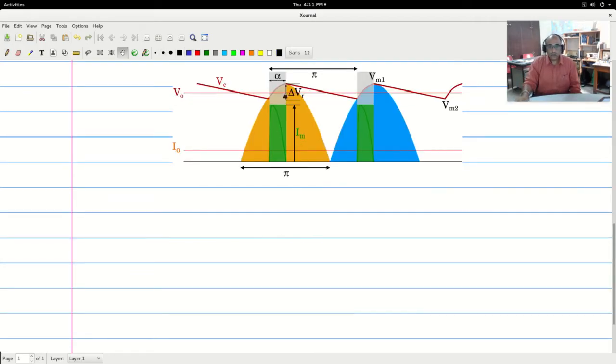Let us start at this point. Let us see what is happening at this point, or shall we come down here, to the corresponding point. So at this point, the capacitor has an energy half C Vm1 square. And from here to here, the diodes are off. Likewise here, from here to here, the diodes are off. The capacitance is doing only the job of discharging into the load.